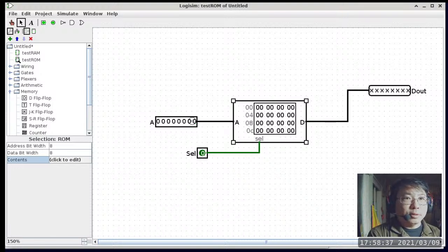So now we can try to specify the address corresponding to 97 and see whether we can get the content back out here, which is supposed to be 7E. So we have to do some base conversion because this is all binary. The input pin and the output pins are binary, but the content in ROM was specified in hexadecimal, and so is the address in ROM.